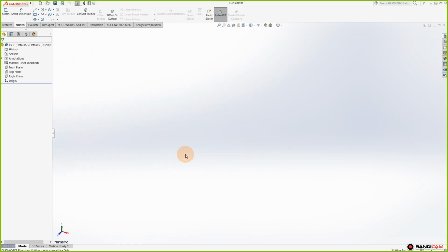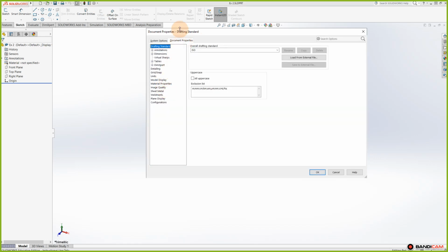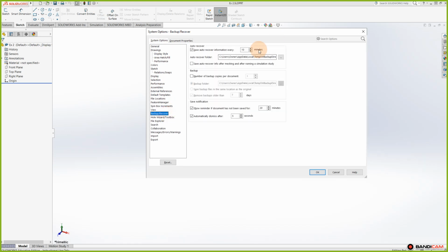And the second you hit Save, you automatically get the auto backups, like we said earlier in the options. Remember, if the documents and where is it? Oh, no, it's under here, System, which is the backup, which means now that I hit save once, in 10 minutes, I'm going to have it automatically saving by itself. So for example, if you lose connection or if it crashes, you only lose 10 minutes of work at a time instead of losing a whole day and so forth. But it's always important that you hit Save for the first time. If you just keep working and you never hit Save, it'll never automatically start saving. It will just wait for you to hit that first save.